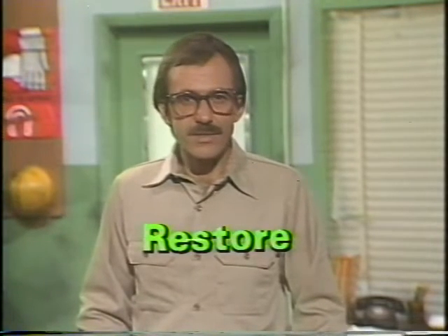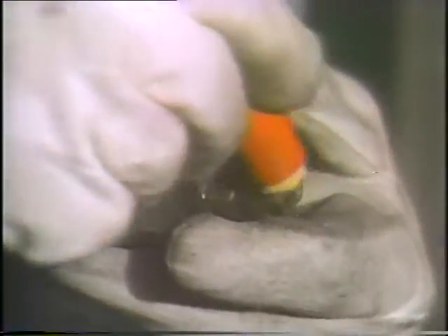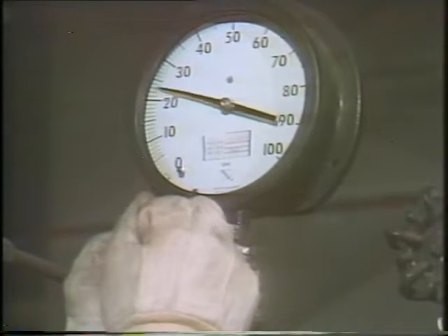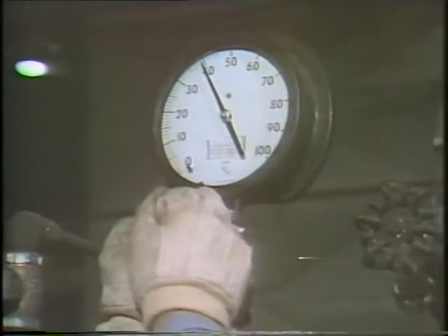After you've removed and repaired the instrument, you need to calibrate it to be sure that it performs properly. Then you need to reinstall it and restore it to service. You should check the instrument service manual for guidelines on how to reinstall it and restore it to service. As you reinstall the instrument, reconnect the supply lines carefully so that you don't cross-thread the connections. Depending on the instrument, you may need to use pipe compounds, sealants, or other protective coatings. Then, once everything is hooked up, open the valve slowly. If you're not careful, you'll apply too much pressure to the instrument too fast, and you could damage it and have to take it right back to the shop again.